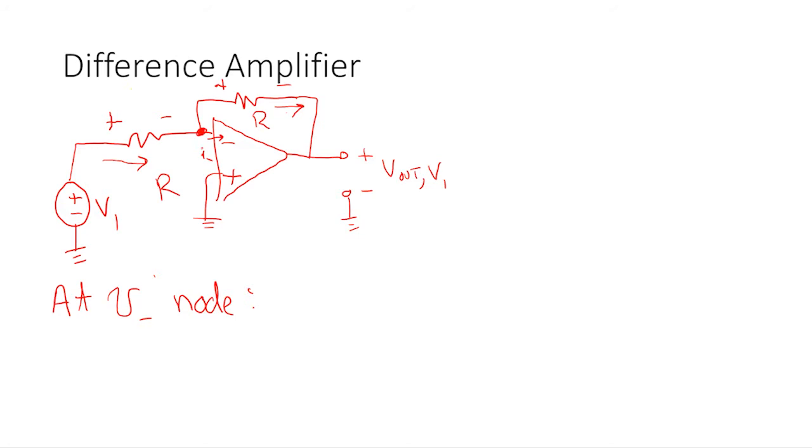I minus is here. I minus is the current going into the op-amp. All right, let me draw it with a capital. Okay. I minus is the current into the minus terminal of the op-amp. So at that node, I have (V1 minus 0) over R. That's a current going into that node, right? And then I have two currents coming out. One of them is I minus. And one of them is what? What's the current in this resistor here? That's, okay, 0 is the voltage at the plus terminal, minus V out is the voltage at the minus terminal, over R.